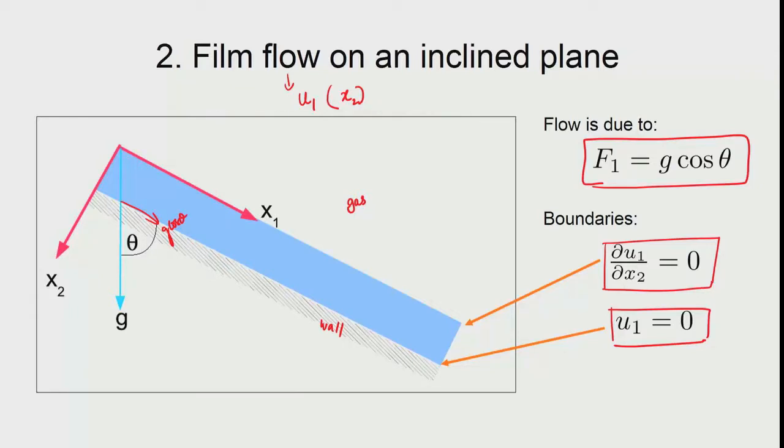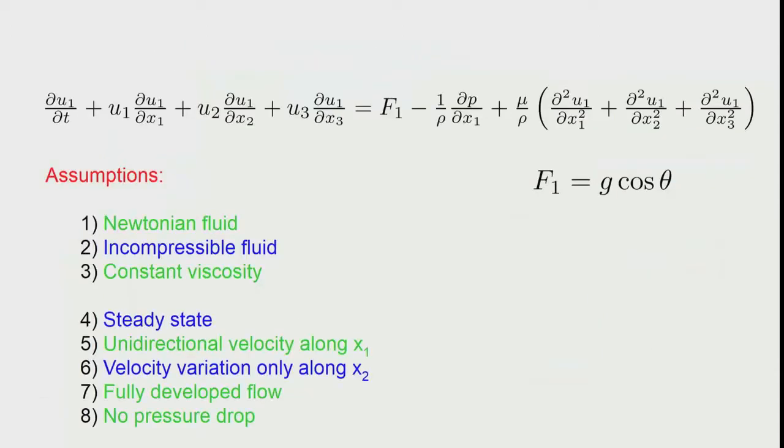So, we can then start the solution by writing the Navier-Stokes equation for the component u1. Here we have the same situation; we have got the equation written already for these 3 assumptions. These are already done, because of which the equation appears in that form, and we assume that this flow is taking place for a long time and at a steady state.